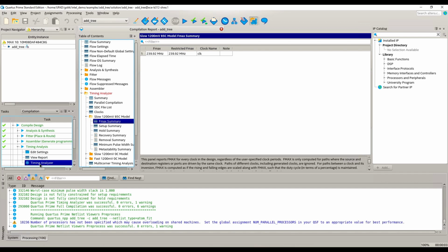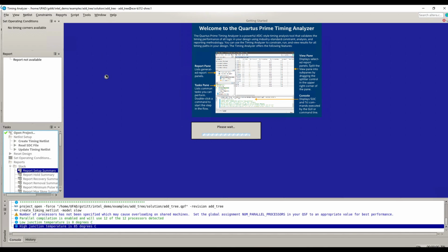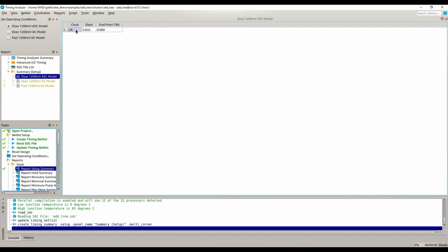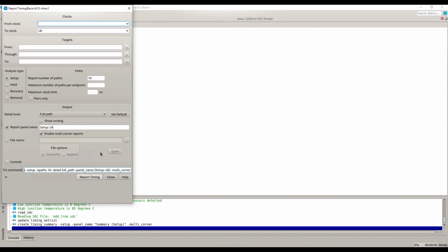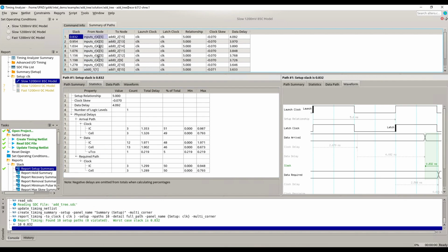Now, really quickly, let's jump into the timing analyzer and just see how things look differently than the previous example, the unoptimized code. All right, so we're going to go through the same steps as before. So this is no longer red because we have a positive slack, and the total negative slack is 0 because we have no timing violations. That's exactly what we wanted to see. All right, so we report the timing. All of these are now black instead of red. That's because they all have positive slack.